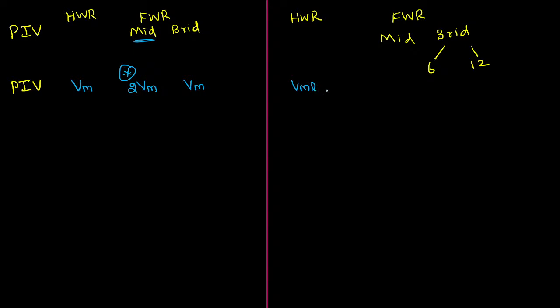If you go ahead with the 6 pulse, that is the midpoint rectifier 6 pulse, it will be blocking 1.155 times the maximum line voltage. A 6 pulse rectifier will be blocking only the maximum line voltage.